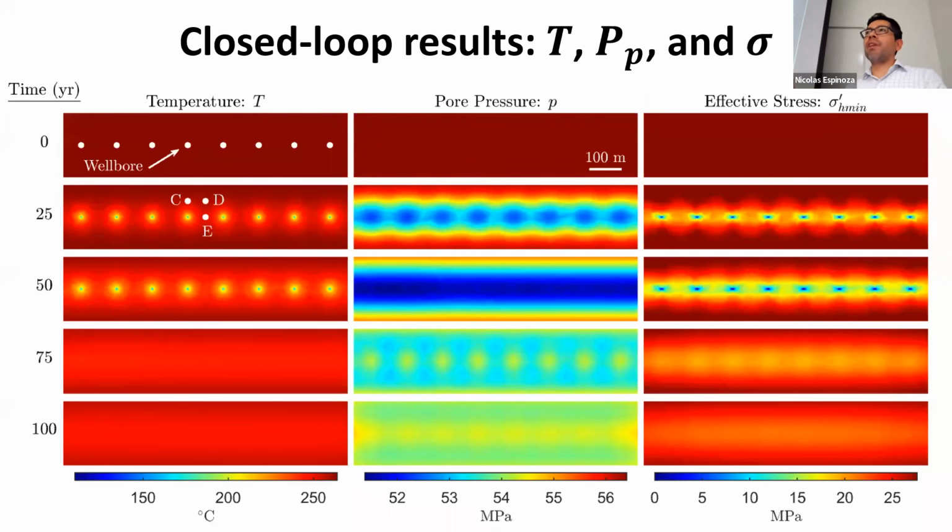And this is this funny effect of the thermal expansion coefficient of the fluid being larger than the thermal expansion coefficient of the rock. It's a few MPa, not that much, but it does change. And effective stresses change too, because of the thermal de-stressing. Now you have a change of the horizontal stress, and also you have the weight of the rock on top, which didn't change, right?